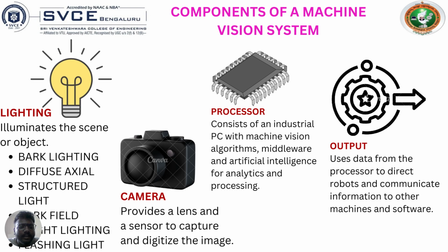For lighting, high contrast applications benefit greatly from bright field light, such as high pressure sodium and quartz light sources, which are very directed but can cast angular shadows, so uniform lighting through the whole field of view is needed. To provide equal light in the bright field, minimizing hot spots and reflections on the reflecting object, a more diffuse light source may be used.